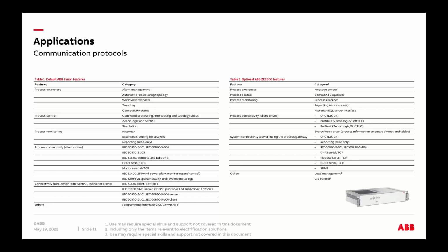For example, if they are relays, if they have, let's say, some Modbus, try to pick Modbus TCP instead of serial, for example. DNP3 as well, do the same thing, and so on. So here you'll see, okay, I have my system, I need to upgrade it to connect it to another system. Now we're talking about an OPC UA type of communication.